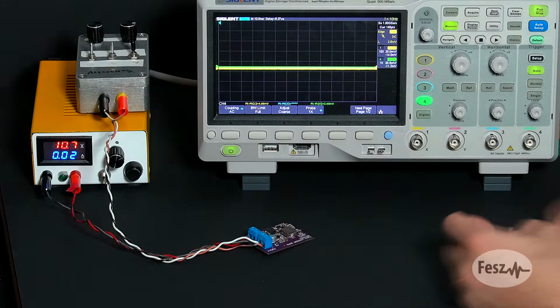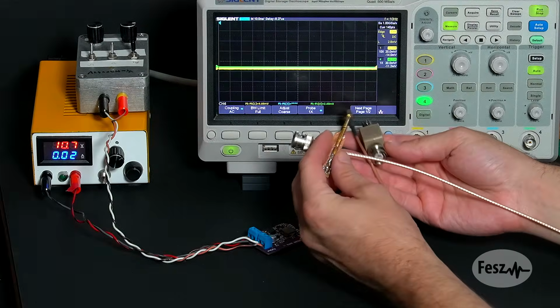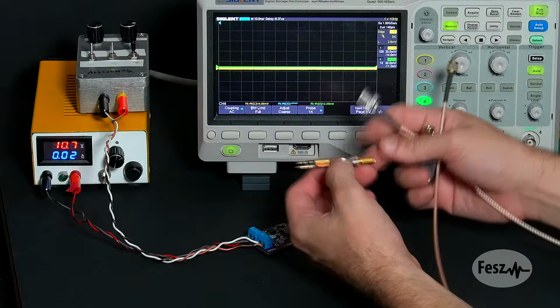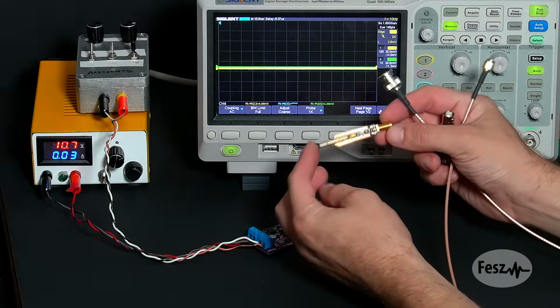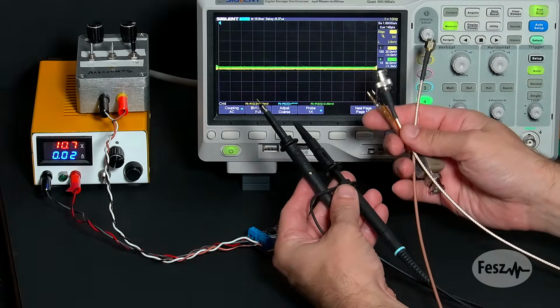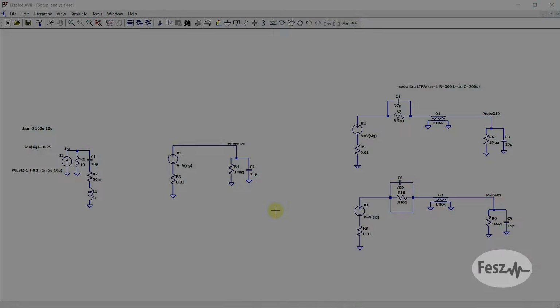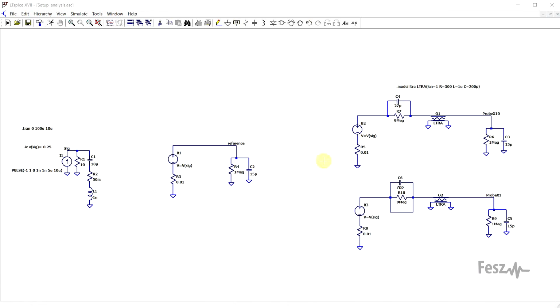While you do have your standard probes in either X10 or X1 configuration, so some probes have the switch, another common way is to use 50 ohm based setups. While I guess you could buy these, it's easier to just homebrew them. Each of these can be used to perform measurements, but the exact choice will be impacted by what exactly you wish to measure.